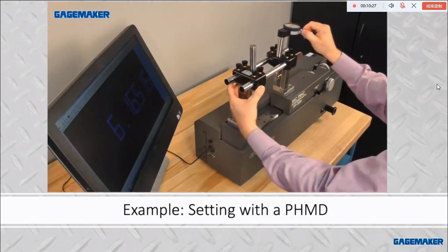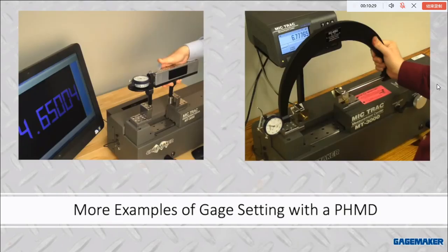But if I want to change the setting value, all I do is dial it in and lock it down again. I don't have to go out and purchase another setting master. Because of the geometry of the fixture, I put the MRP gauge on, I take it off the face, I zero the dial. Don't really have to do any gross sweeping like I would with a micrometer or a set of gauge blocks. Very robust, very simple, too easy.